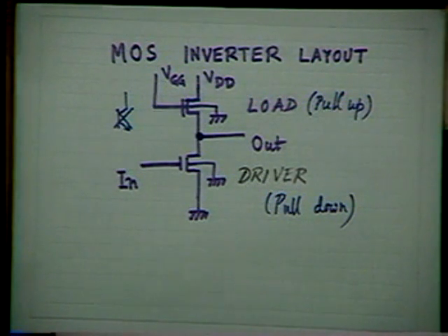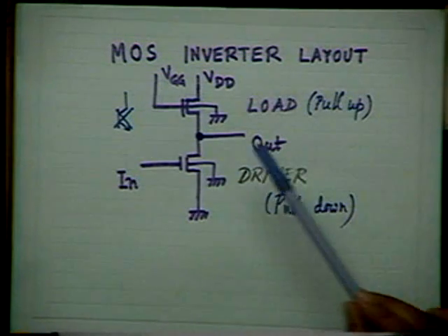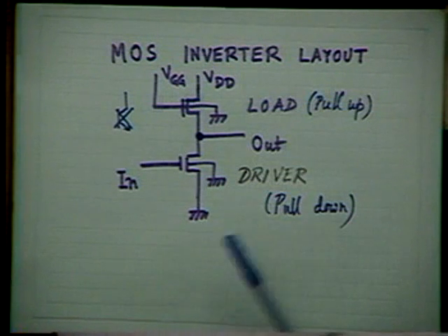That means you have to apply a positive bias to repel holes and attract electrons, and ultimately above a certain bias called threshold voltage at the gate, the channel gets inverted. Means there will be a lot of electrons near the surface. This electron sheath connects the source and drain, and that's how we say that the switch is on. So an enhancement mode nMOS operates with VDD and VGG, drain bias and gate bias, both of positive polarity with respect to the source.